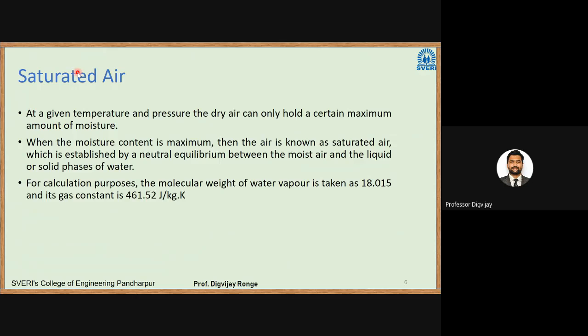So what is happening in that case? Actually, these water particles are getting condensed on the cool surface of the Coke or Pepsi bottle. So it depends on the temperature. If I reduce the temperature of atmospheric air, one point will come at which the water particles will be saturated. If I reduce the temperature just a little bit after that point, the water particles will start to condense. But before condensation, whatever condition it is, we refer to that condition as a saturated condition.